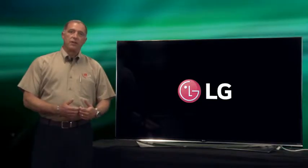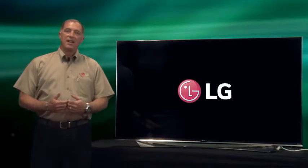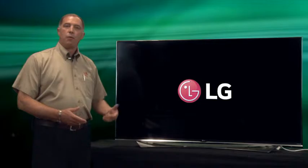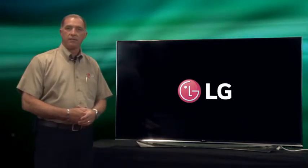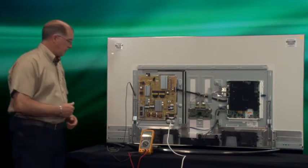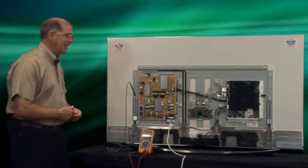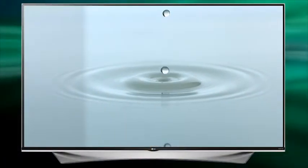You can check the voltage on each one of those and monitor that return voltage. That's going to tell you multiple things depending on what your symptom is. Now we'll move to the power supply and look at some of the voltages coming off of the return lines for the inverter. Now, a quick way to determine whether the LEDs are responsive, if they're too dim, if you isolate what segment of LEDs is not performing correctly, say you've got a dark section of the picture.